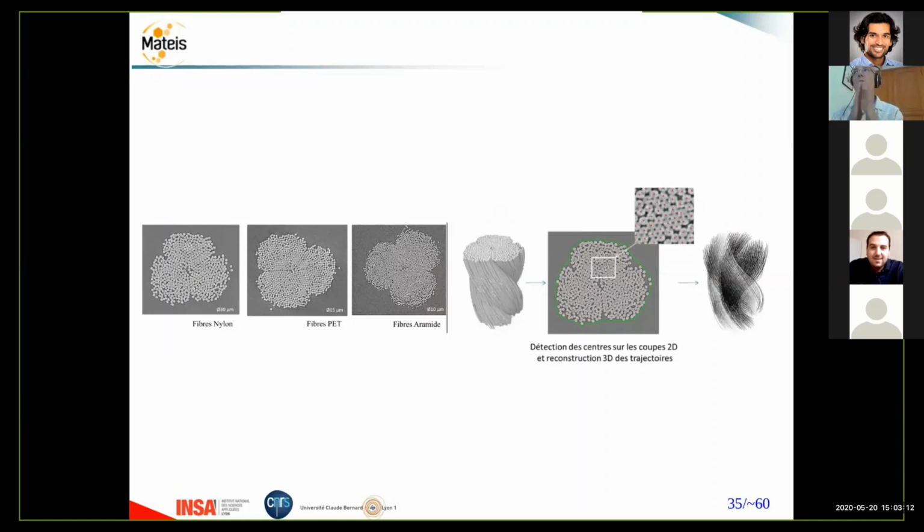All the fibers are nearly parallel and you pull on the fibers. There is a little bit of sliding, but much less than if you have a wool, for example. If you have fibers in every direction, with contacts like this, then friction is dominant on the behavior. But if all your fibers are like this and you pull like this, this is the reason why we didn't try to calculate or simulate the friction.